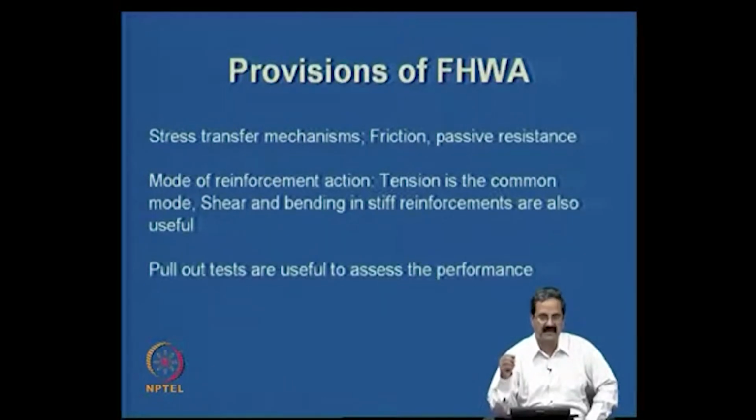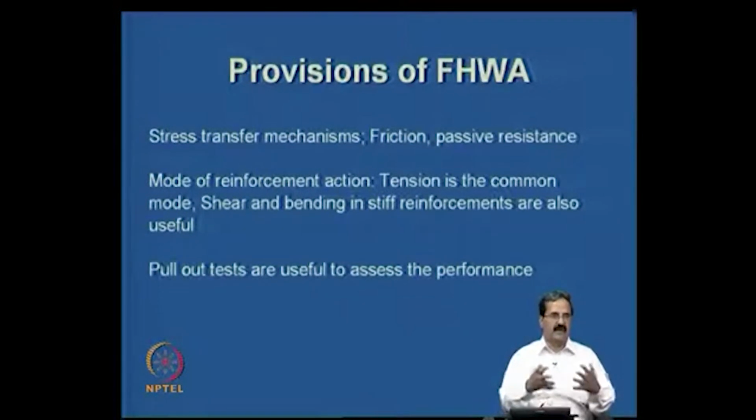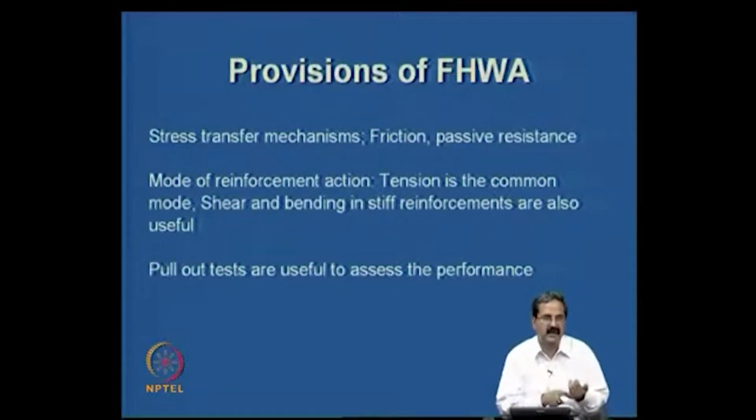But then suppose you have a stiffer reinforcement. We have two types of materials. In fact, there are many nowadays. You can even have composite reinforcements also. What it means is that, I told you, geogrids are an extensible type of reinforcement. Geotextiles are an extensible type of reinforcement. Whereas steel is not extensible compared to the stiffness that you have in the case of geotextiles, it's much stiffer. So you may call it non-extensible, but then you also have a combination of what are called anchor plates.